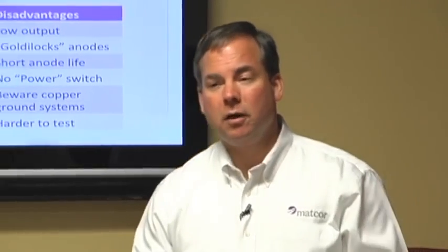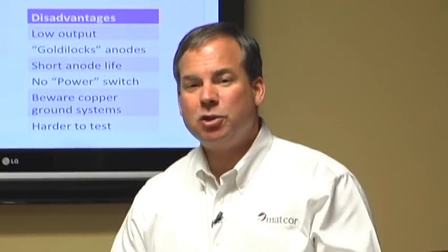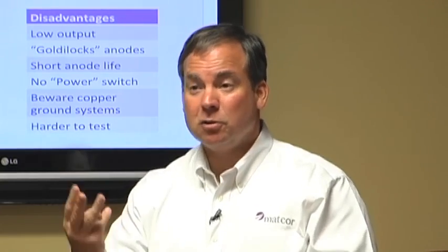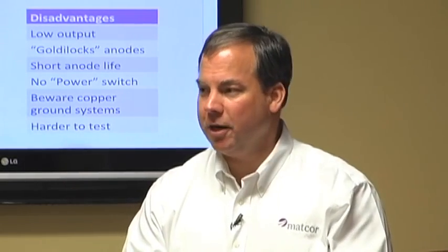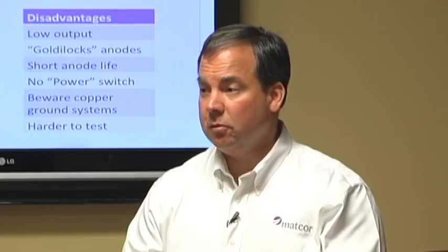They tend to have shorter anode life. I don't have a lot of choices for what anode material it is. There's those 3 metals, magnesium, aluminum, zinc, that are more negative than steel. I can't use anything else.